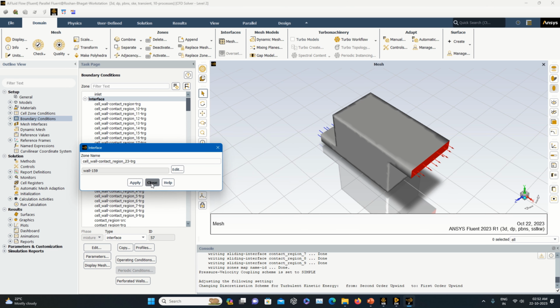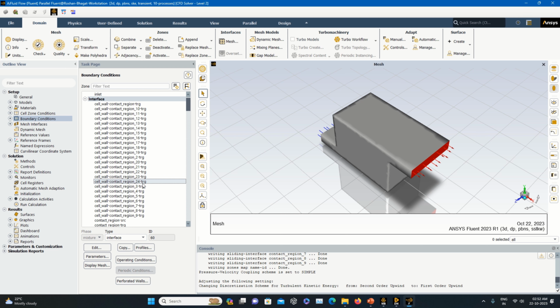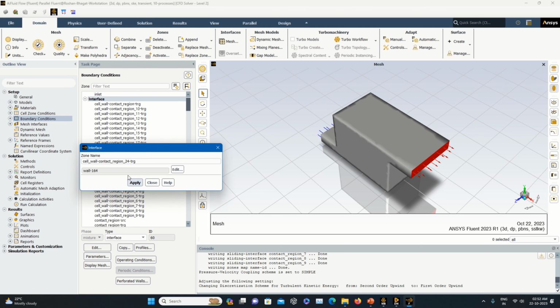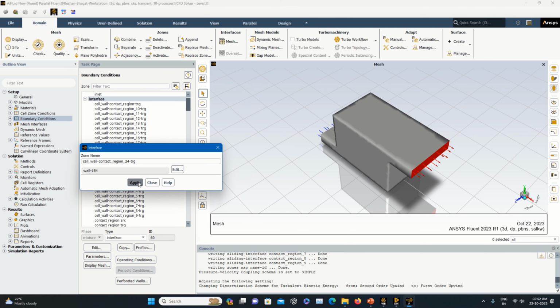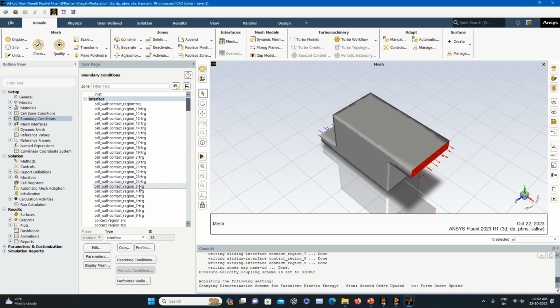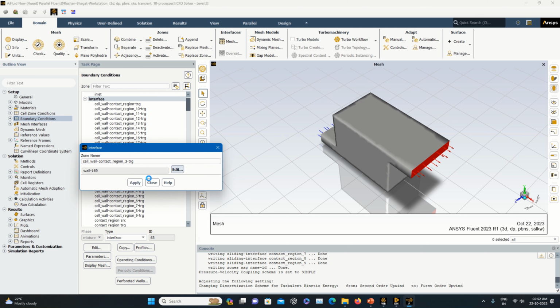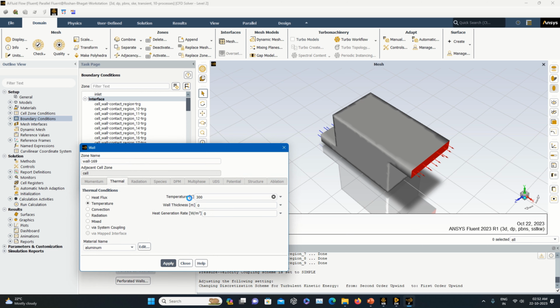If it is going in the right way, you can definitely go on to update the mesh size. If you update it at the initial stage, the simulation may take time, and checking whether it is going in the right way can also take time. So that's why I put a comparatively default mesh which is generated by the computer, but definitely you can change it to the requirement as per your case.